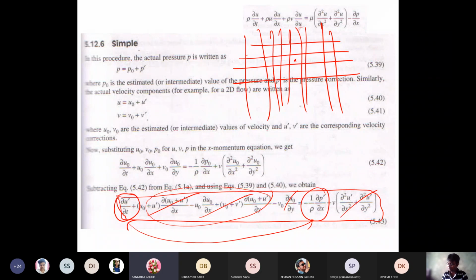Let's say you are considering this cell, and you are doing the correction on this particular cell. Now, the velocity correction on this cell will have very little influence on a cell located far away. So this cell's velocity and pressure will be mostly guided by the surrounding neighbors only. The cells which are far away will not have a very strong influence on this. So this is not required at all, physically, if you think. If you consider only the surrounding cells, this is good enough.